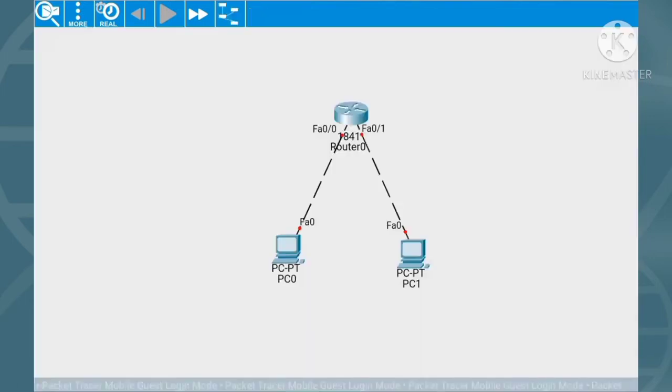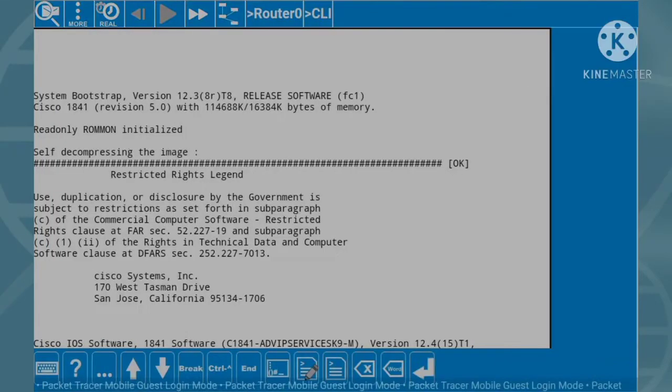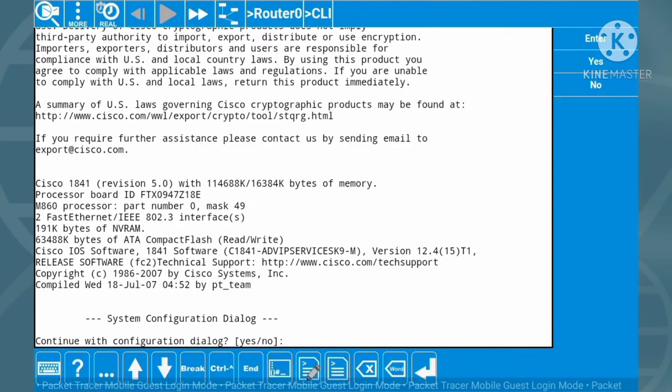Now, configuring a router. At this point, the router still needs to be turned on, which in this case you don't need to, because once you select a router, it's automatically turned on. Currently, they are physically connected but inactive, in a state referred to as administrative shutdown. Single tap on the router, then select CLI to open the configuration menu.